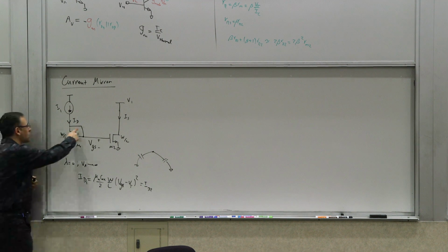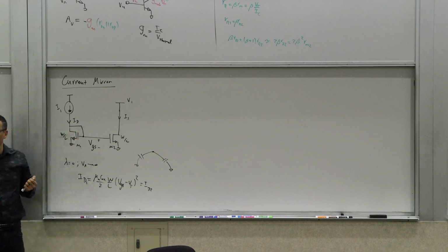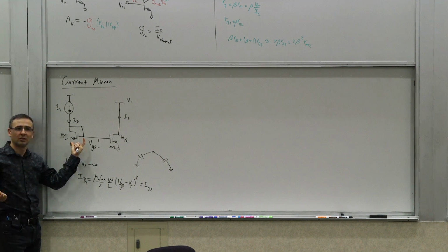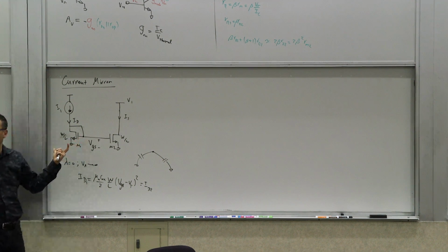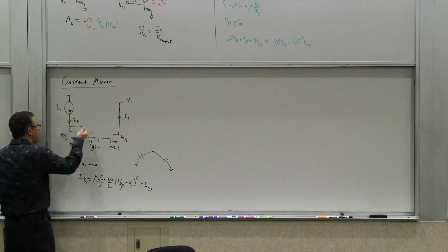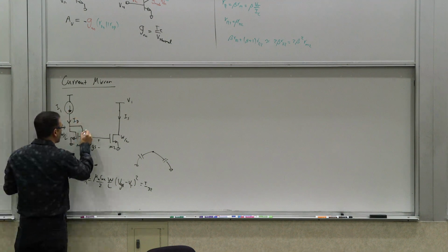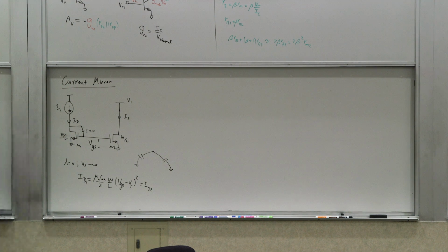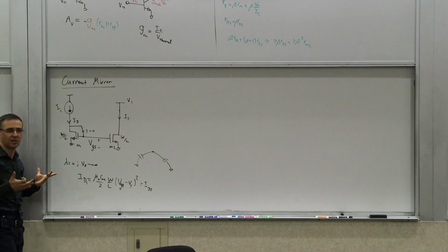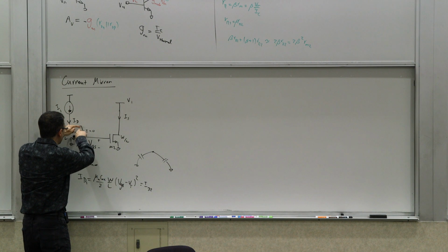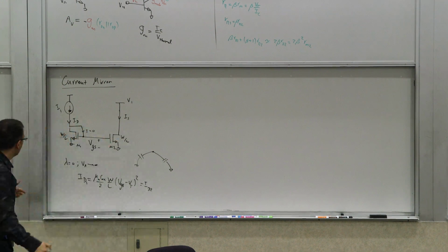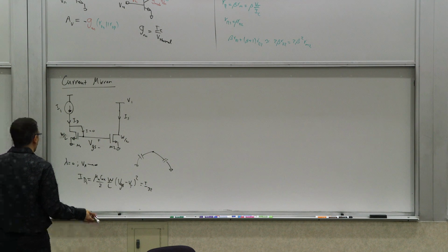And by the way, this also guarantees that if your threshold is positive, the transistor will never enter triode region. It will either be in pinch off or off. So when you feed this current, now in the case of a MOSFET, there will be no current flowing through here. No DC current in the classic MOSFET sense. And if there is a bipolar, some of that current is actually supplied through here, some of that base current. So this is what we call a current mirror.